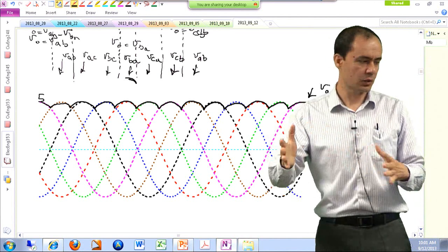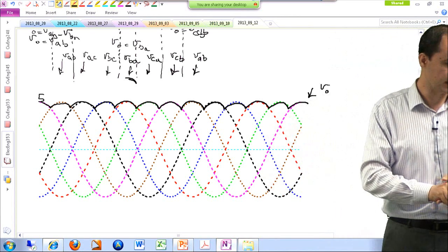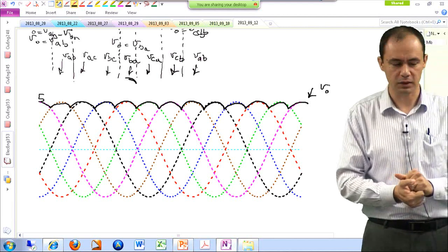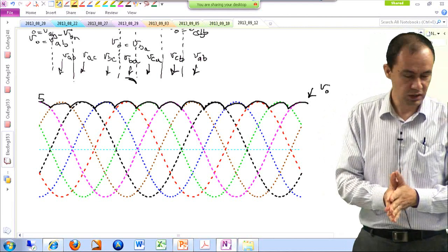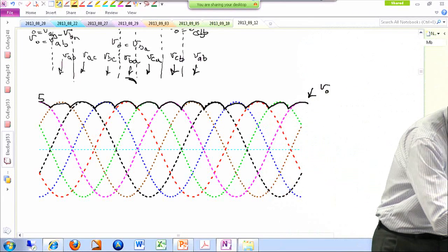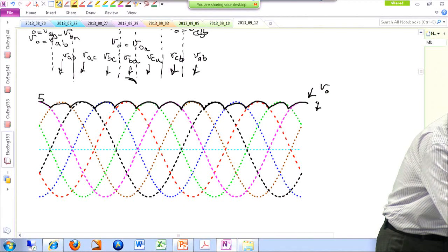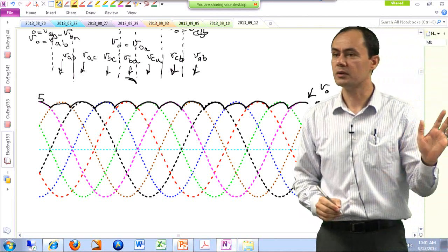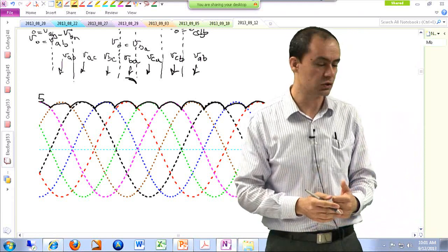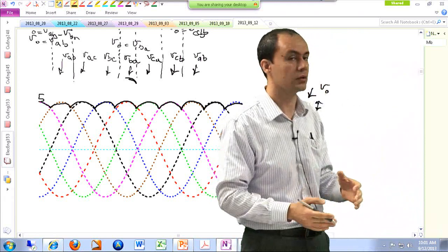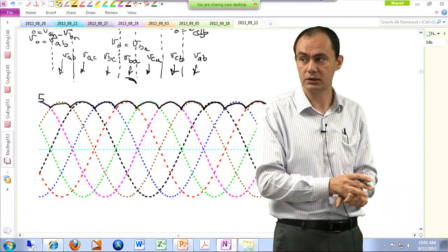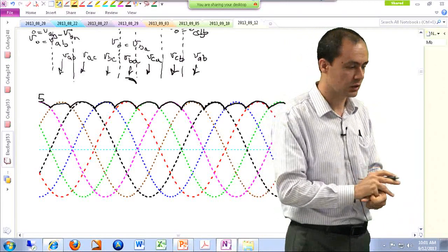So if you look at a sequence, the output voltage first follows VAB, then VAC, then VBC, VBA, VCA, and VCB. Okay. Several notes. The output voltage is relatively DC. It doesn't have a lot of ripple. See the ripple. We just have a tiny little ripple over here. And please remember, we just used the resistor as our load. We did not even try to make it fancier using an inductor in series with the load or using a capacitor in parallel with the load. It is actually still a good DC signal, even though our load is a purely resistive load.